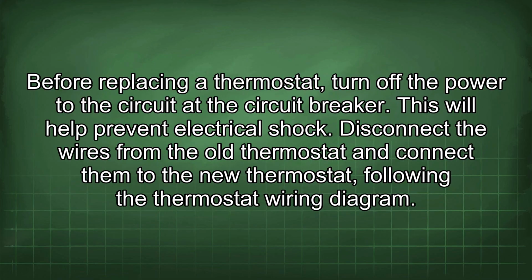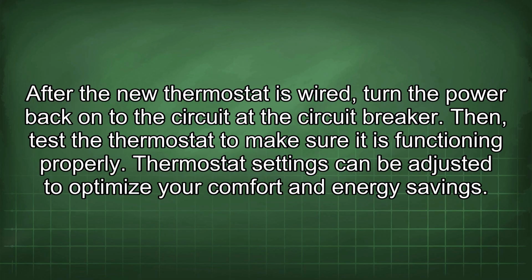Before replacing a thermostat, turn off the power to the circuit at the circuit breaker. This will help prevent electrical shock. Disconnect the wires from the old thermostat and connect them to the new thermostat following the thermostat wiring diagram. After the new thermostat is wired, turn the power back onto the circuit at the circuit breaker. Then test the thermostat to make sure it is functioning properly.